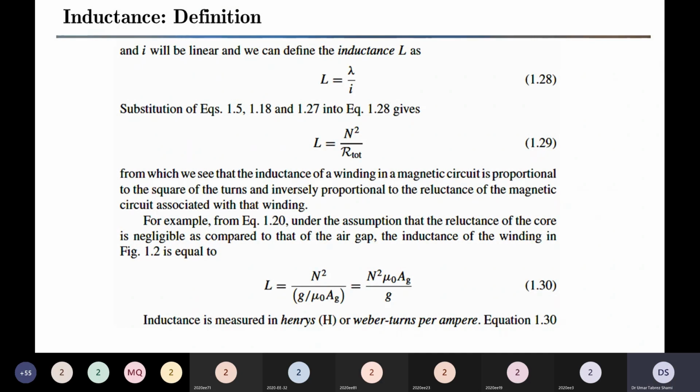It defines the relationship between the number of turns and the geometry of the magnetic material, और इसको आप बोलते हैं इंडक्टेंस. इंडक्टेंस कॉइल की होती है, जो कॉइल आप इस्तेमाल कर रहे हैं, जो सोर्स है फ्लक्स का, इंडक्टेंस हमेशा कॉइल की होती है. और वो क्या होता है? That is equal to number of turns of the coil divided by the total reluctance in the magnetic circuit. ठीक है, ओके. एक बात ये क्लियर होगी.